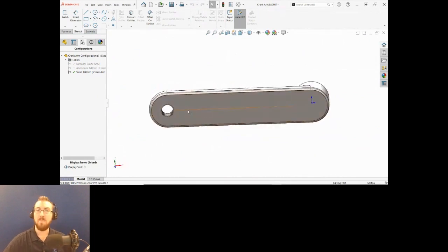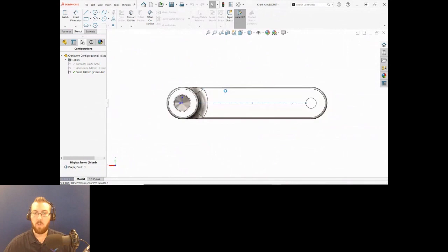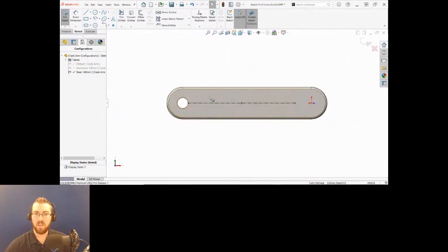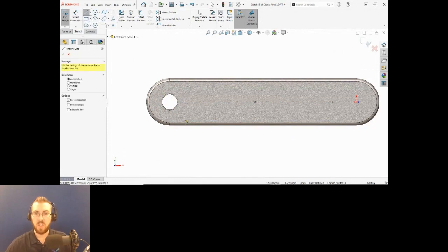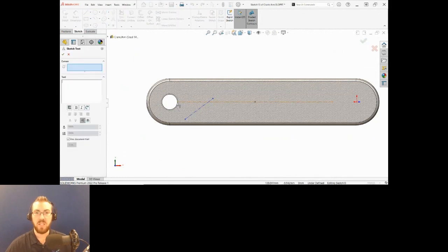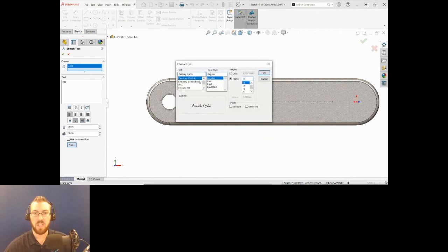We're going to have that debossed branded text. I want to show how we can now pattern text. And this was simply a limitation in previous years. So I'm editing a construction line sketch that I've got back here, and we're going to add in our own construction line. This is just going to be used as the curve for holding our text. We'll do HRS for Hawkridge Systems, flip that around, and I've got the 3DS font installed on my system. So I think that would be a good look here.